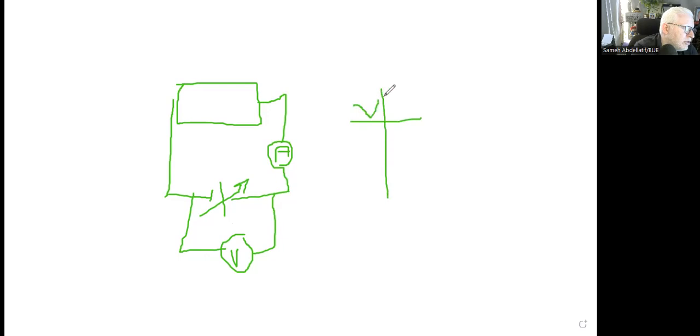And in parallel, you are going to connect a voltmeter, as you know from your basic electronics or circuits class. So you are going to vary this voltage and then record the voltage value using the voltmeter and the current value using the ammeter, and you will have a table like that. So we have a certain voltage and a certain current, and you can plot this graph.